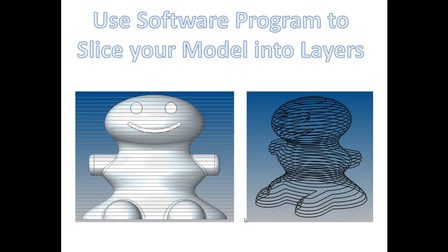Once you have a model, you need that software that's going to slice it up. At the beginning, we said 3D printing is layered manufacturing. What 3D printing really is, is taking an object, like Ovid there on the left, drawing a bunch of lines across him, and calculating the intersection of those lines and the object. Then we can build them up one layer at a time. That's why it's called layered manufacturing. If you look on the right, you can see the layers for Ovid if we use a pretty coarse 3D printer. So the layers are pretty thick.